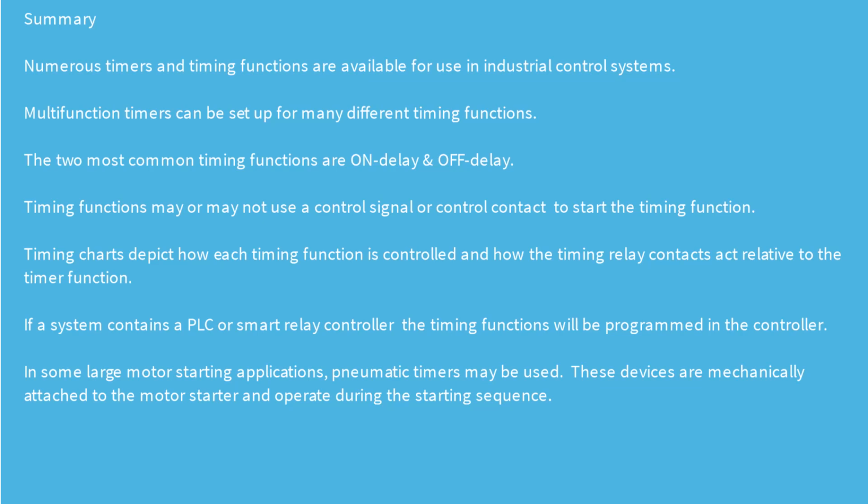If a system contains a PLC or smart relay controller, the timing functions will be programmed in the controller. In some large motor starting applications, pneumatic timers may be used. These devices are mechanically attached to the motor starter and operate during the starting sequence.